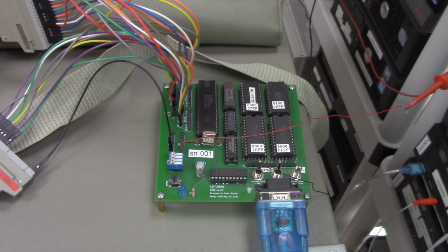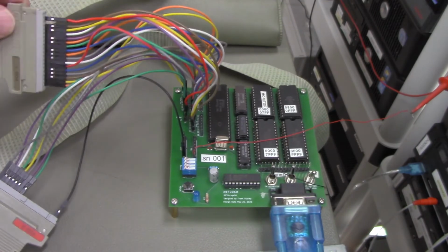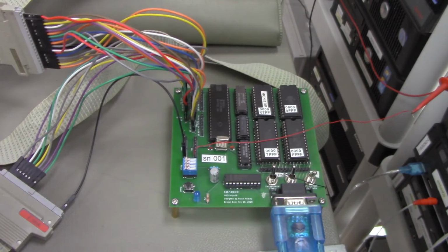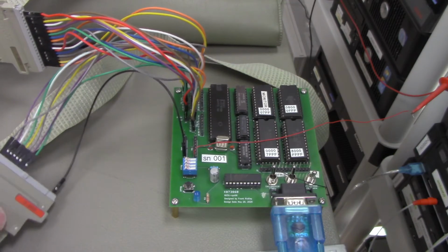Today we're going to talk about my 8031 computer system, which is connected to a 16500C Logic Analyzer. So this is an HP16500C Logic Analyzer, and it has a 25 megahertz state analyzer in it. The part number of the state analyzer module that's in there is an HP16500A. Pod 1 is connected to the address bus, and pod 2 is connected to the data bus.